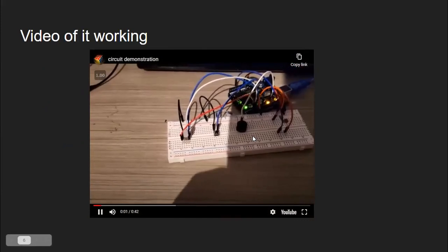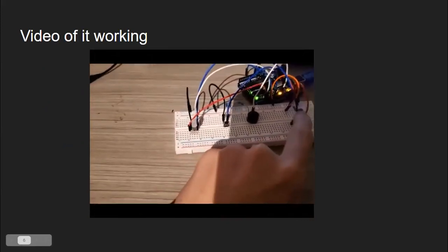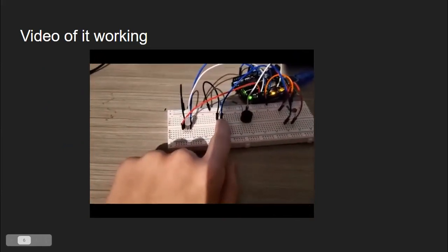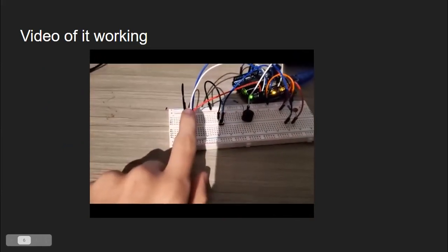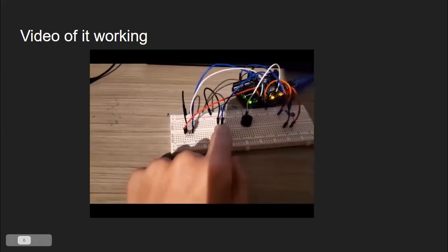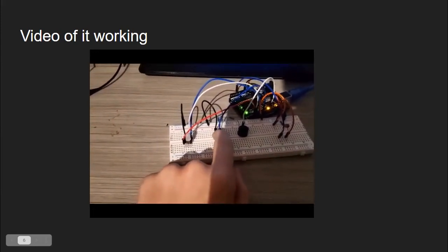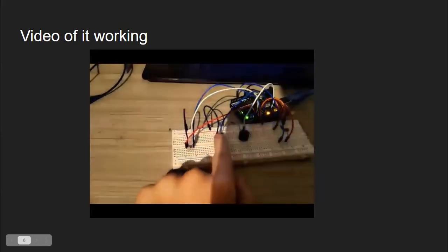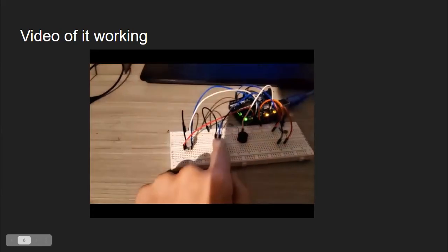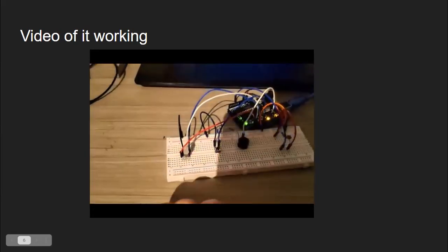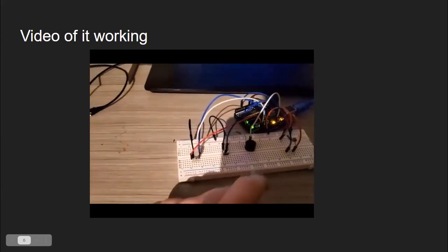Here I have my Arduino and circuit. I have my photoresistor here on the right, the piezo element, the push button, and the indicator LED. Currently it's not going off because my tablet is covering the light to the photoresistor. I can scroll through the tunes with this push button. There we go. Again and again. So if it ends on blue, it will play the Jigglypuff theme.